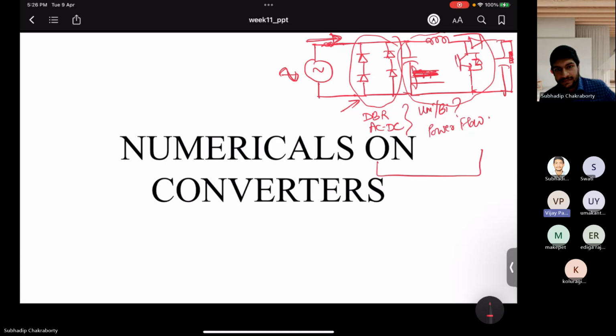One diode we have to put in parallel with the system. Correct. So that is one arrangement you can do. But are the diodes controllable devices? Can you control the diodes? No. Can you control their turn off and turn on? Because that is very much necessary for your power factor correction. Because you have to use some control arrangements.